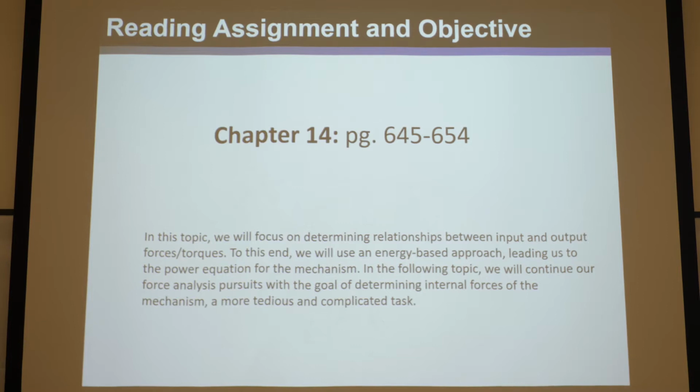So not internal forces. Using this approach, I'll emphasize you can't really tell much about the forces that are going on inside the mechanism. The internal forces, like the force inside a link that you need to analyze if it's about to yield or break or buckle. This approach you can't use to determine that. Just the external forces, the forces you externally apply, and that the mechanism as a response externally applies to something external as an output. If you don't know what internal and external forces are, we'll talk about those. But just to emphasize, energy lecture, dealing with external forces, okay?